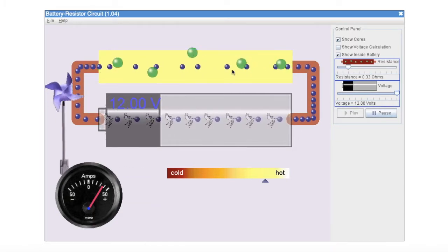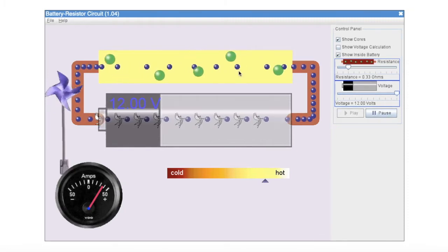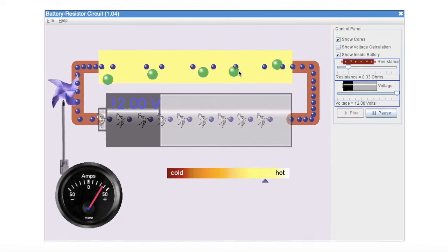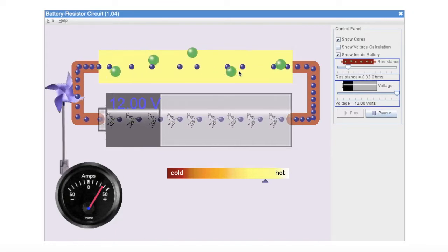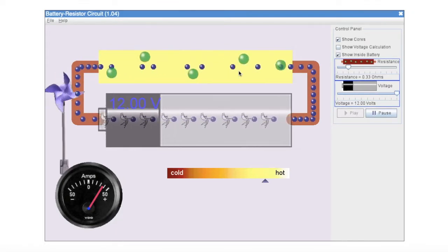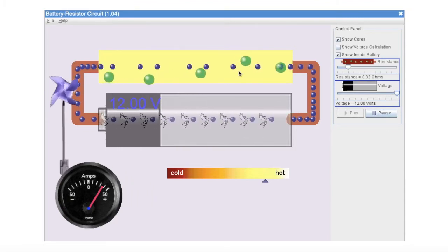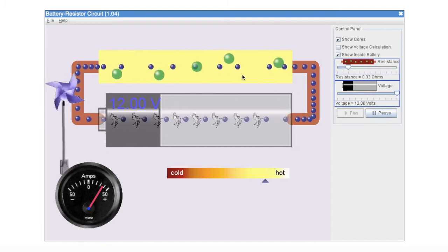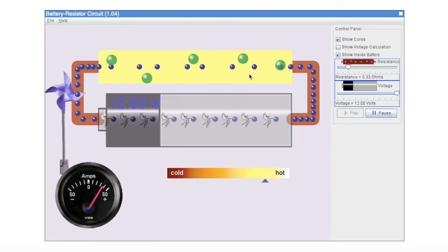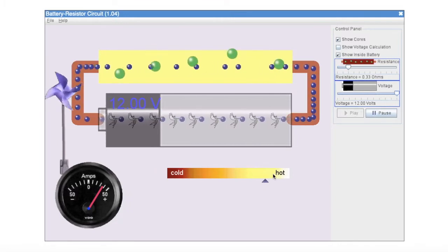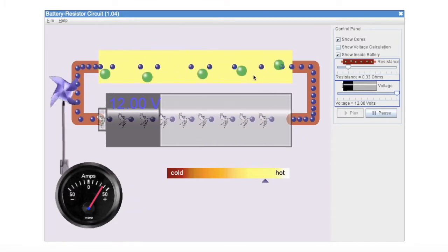Therefore, they are intercepting the passage of the electrons furthermore, which is basically an indication of what? If you are intercepting the passage of the electrical current furthermore, that implies that you are hindering or impeding the passage of the electrons. Therefore, what you are actually doing is increasing the resistance of that conductor. As we can see, an increment in temperature was accompanied by an increment in resistance.